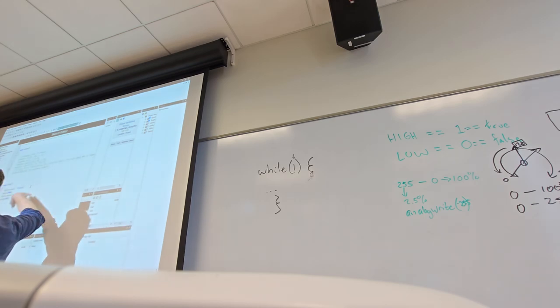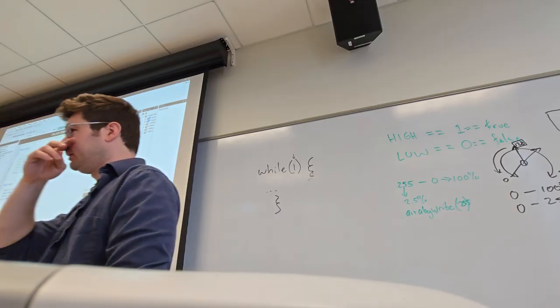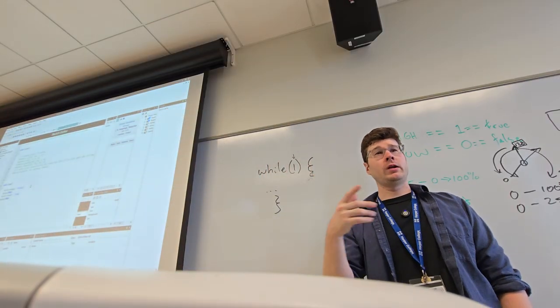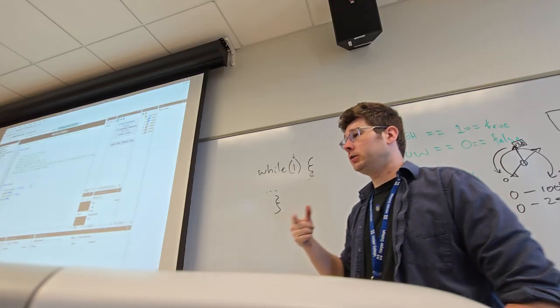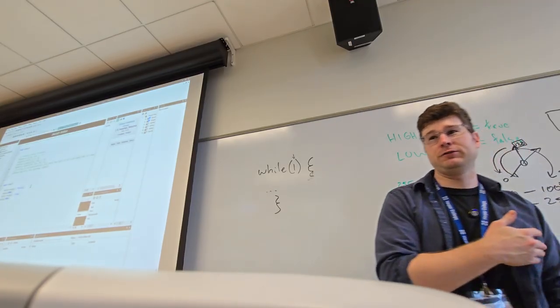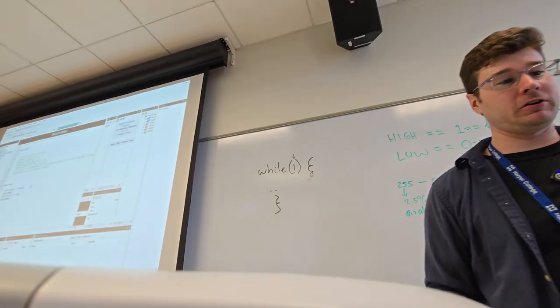Whatever we run in here will run, and it'll run as fast as it possibly can. It's not like a PLC program where it runs every 10 milliseconds or whenever we schedule it to. It'll just run and run and run, kind of like a typical Arduino runs, as fast as the little thing can, at 16 megahertz, at 60 megahertz, whatever.